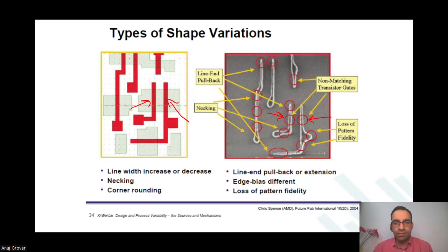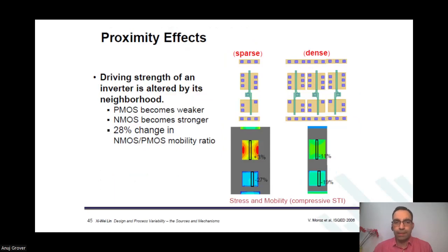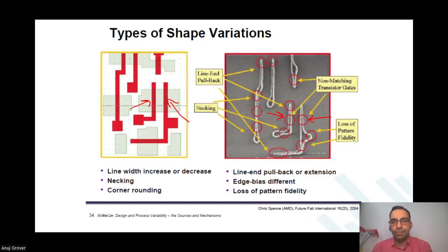Are you able to see this? So the length of the right gate is bigger, right? Because it is extended to the other diffusion also. So we are looking at the gate region, only above the diffusion layer, not outside the gate region. In this case, the diffusion layer would be something like this. If I just draw it, it would be something like this.